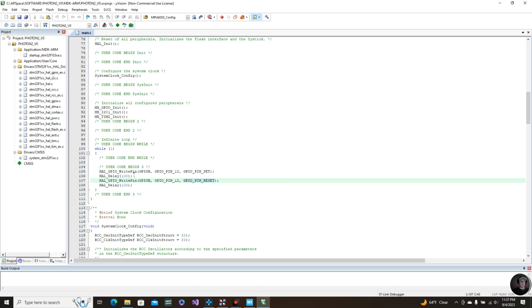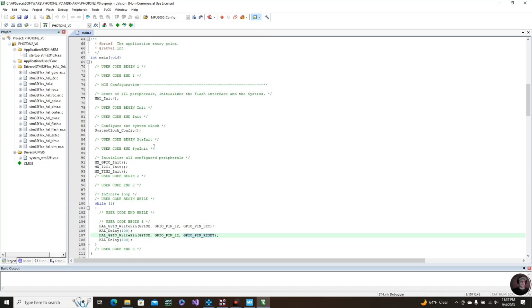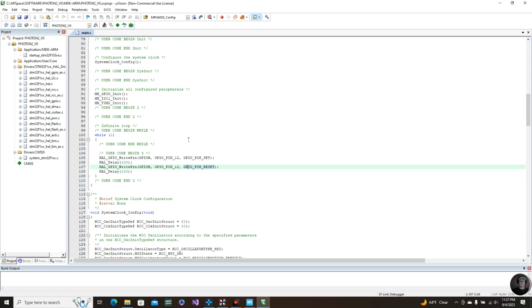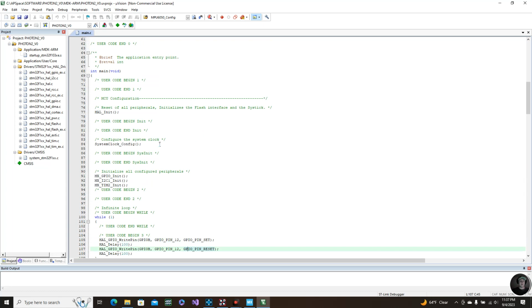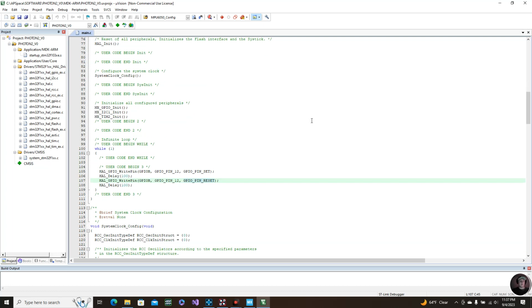And then everything that we need to configure is all in this while loop here, okay? So really where we could write everything is either in this while loop if the script needs to configure the GPIO on and off multiple times. If not, you can configure it somewhere in init, depending upon your application.